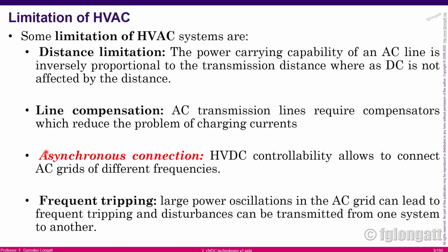That can create an isolation in terms of synchronism, or what we call a synchronous connection. And on the other terminal, we use the DC and convert and then go back to the AC system. But the interesting thing is, in this conversion, AC to DC, DC to AC, we can have more controllability. We have probably full controllability of the power that is moving through the transmission line, the DC transmission line. And that is something that is not easy if you are using AC signals.